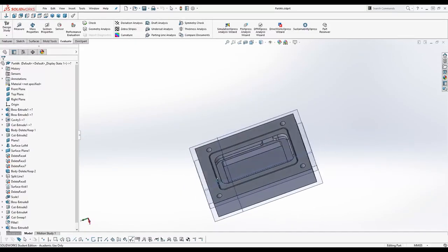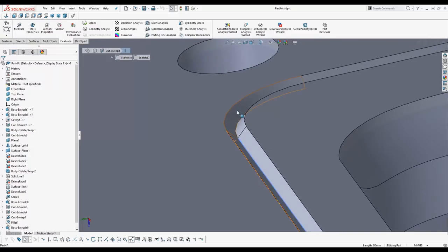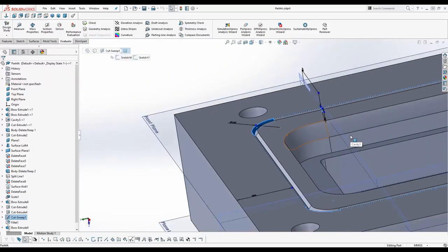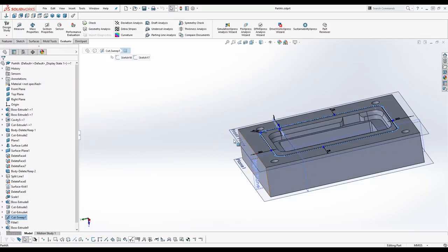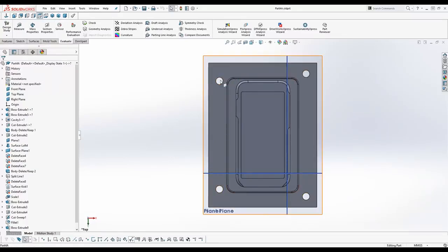Another feature is a lip and groove on the mold. This is the groove, and the other side of the mold has the lip. With this you make sure that your mold halves accurately fit together so that they cannot move from each other. There are also 4 mounting holes. These are 4 bolts to clamp the mold together. Otherwise you have the possibility of plastic flowing outside of the cavity and in between the 2 mold halves. As you can see, I placed the mounting holes asymmetrical so that it's not possible to flip one of the mold halves and connect it in a wrong way.